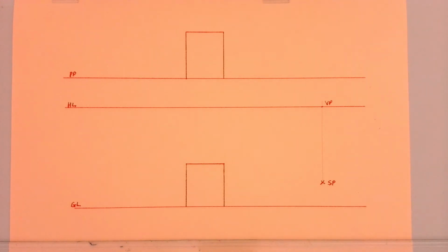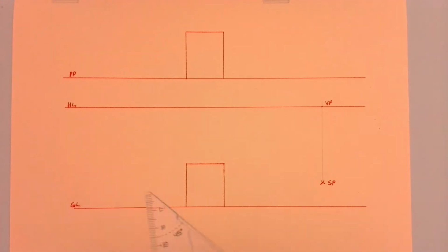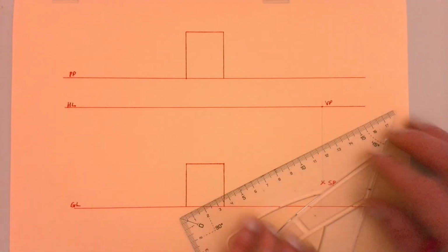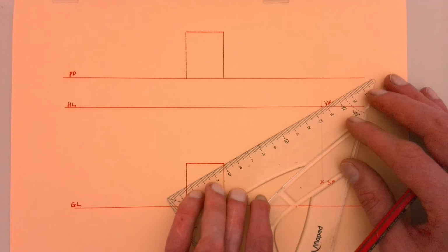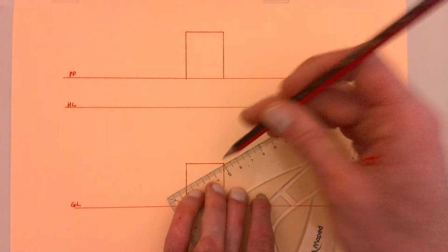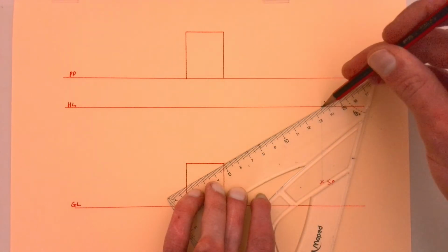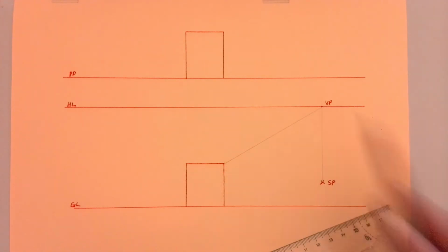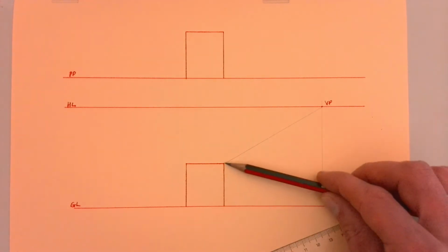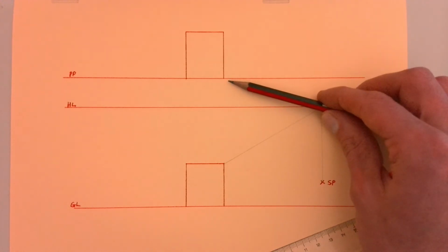Now, to start us off, we are going to take the points, or the corners, we have in our front view, and we're going to take them one at a time to our vanishing point with a construction line. So we're going to draw a construction line from our corner to our vanishing point, and then we're going to say to ourselves, now which point over here in our front view is represented in our top view.